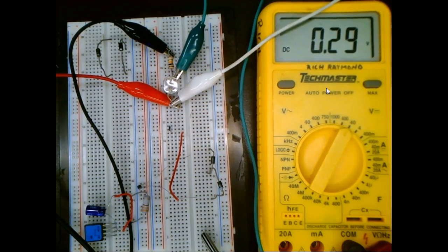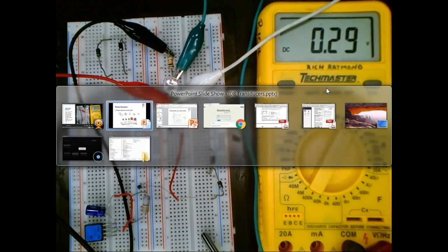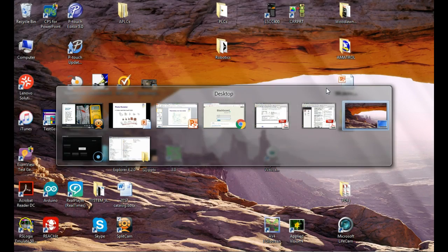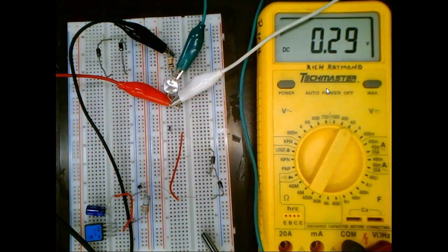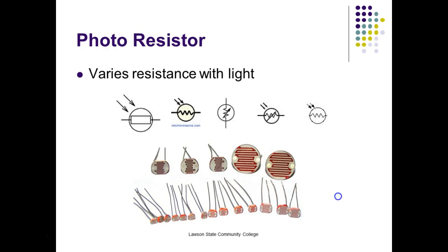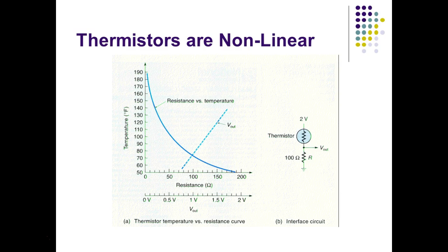If you put it in a Wheatstone bridge, and what's nice about a Wheatstone bridge is, where's my PowerPoint? Here. What's nice about a Wheatstone bridge is that it would actually go negative. So we said I could put it in a glass of ice water and set 0. Well, what happens if it goes to minus 5 degrees? Well, my voltage would go minus, right? You understand? But it would still have the same ratio that we figured out before.